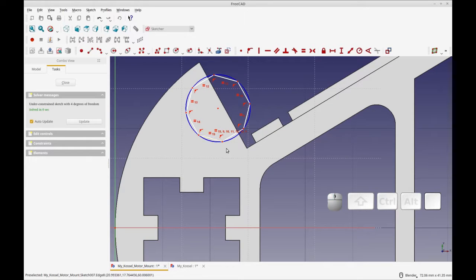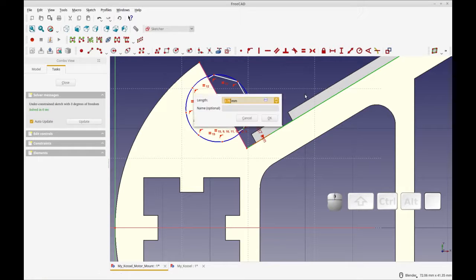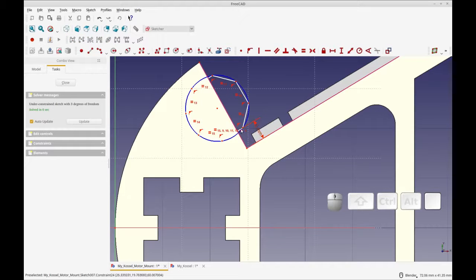and we'll select some external geometries. So the first external geometry, or the only external, I think we need this one, and maybe this one. I'll delete it if we don't need it. So the first thing we're going to do is set the distance from this internal edge. It's going to be 4 millimeters. Oops, it's going to be from this line. Okay. So that'll line up with the structure of the 2020 extrusion.